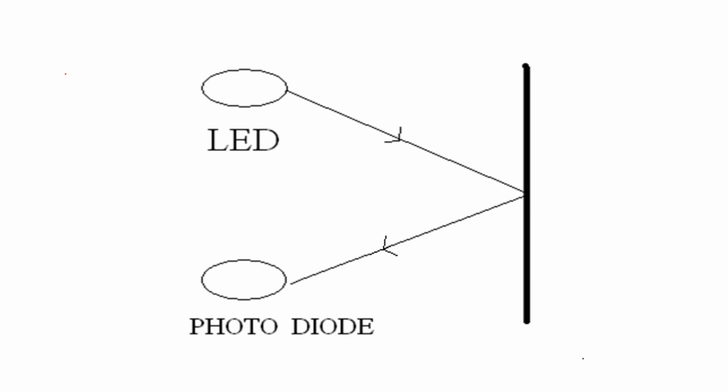You see, pins A0 to A5 are the ones on which we are connecting to the Arduino. We can connect our sensor anywhere from A0, A1, A2, A3, A4, A5. Now, all these pins contain ADC. They contain what? ADC.